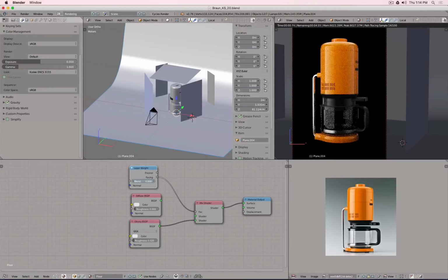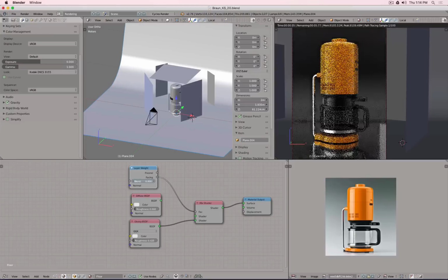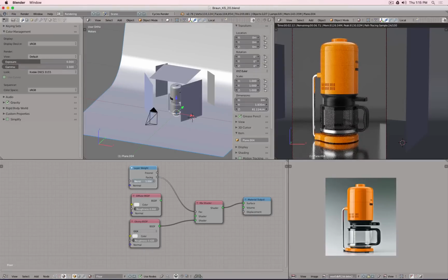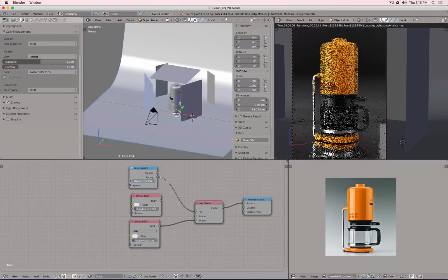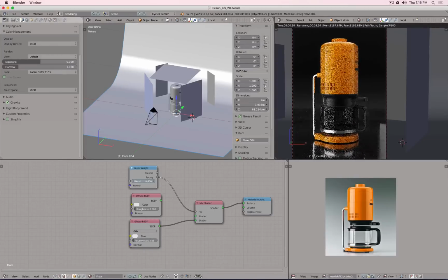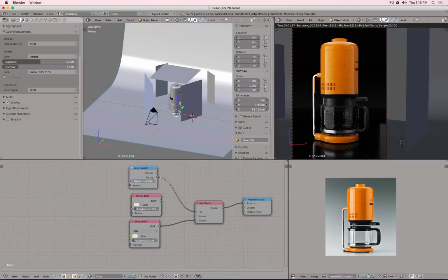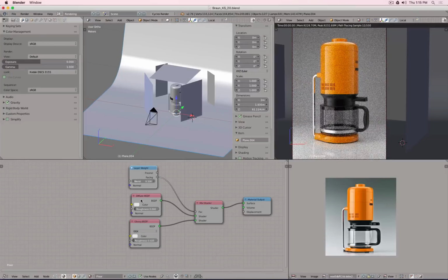When, for example, I turn the blend value to 0, or if I set it to 1, now you can see even the vertical face of my backdrop has a reflectivity value, and if I lower this one, at one point only the ground plane, for example, is a little bit reflective, but not really the backdrop, which is very good because now this only reflects the object and the backdrop only shows the color from my diffuse and has no, let's say, reflectivity added to it.